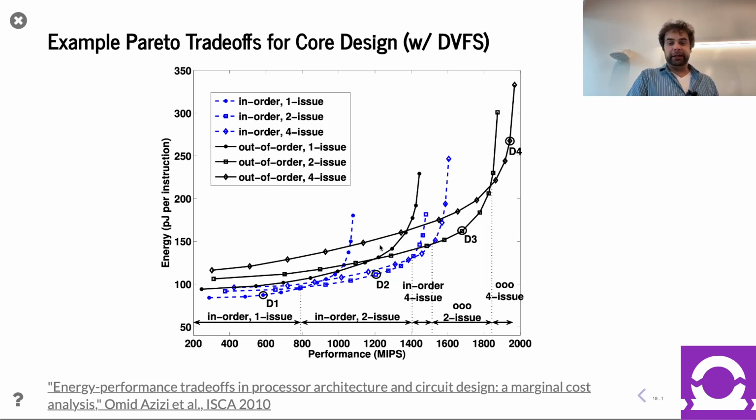Like I said, you see different processors have their moment. For a given processor, depending on how you're pushing frequency, it's a linear regime, and then it blows up on you, right? So you maybe want to avoid the blow-up regime. But it's very pleasing, this data. You see, oh yeah, if I want a small amount of energy and I don't mind about performance, the best thing I can do is 1 wide in-order. If we want a bit more performance, a 2 wide in-order is a really good sweet spot. Technically, there's a small window here in which the in-order 4 wide wins.